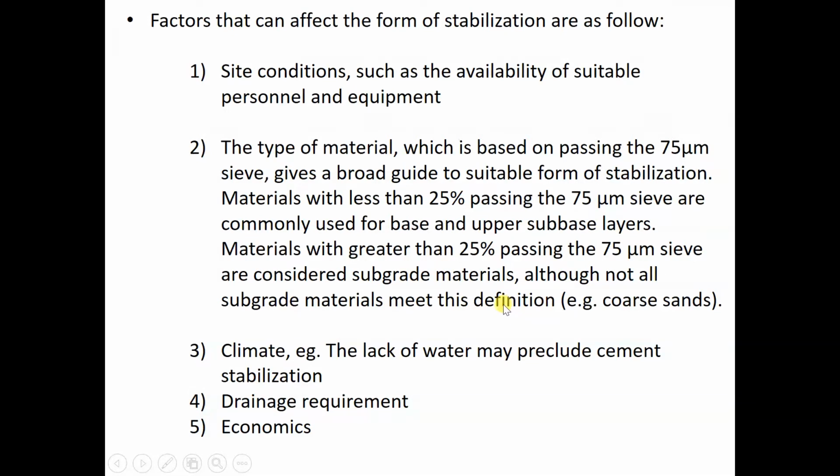The pavement usually has a cross fall, so the water can run from the middle of the road to the edge of the road, along the top of the stabilized layer.